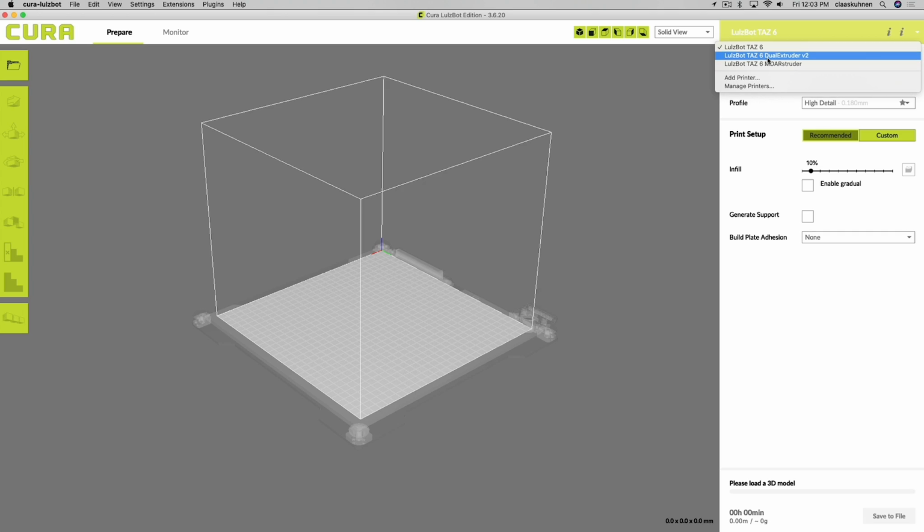The dual extruder is really nice when I would like to print with PLA for the object and water dissolvable material for the support, so I could wash it away. Very good when I want to print a piece inside a piece. And the standard extruder is just a small nozzle, very good for fine details, but obviously that also means longer print time. So what we will focus on first is how we select the print material, how we specify the nozzle size and the layer height, and what all this will mean for our print.